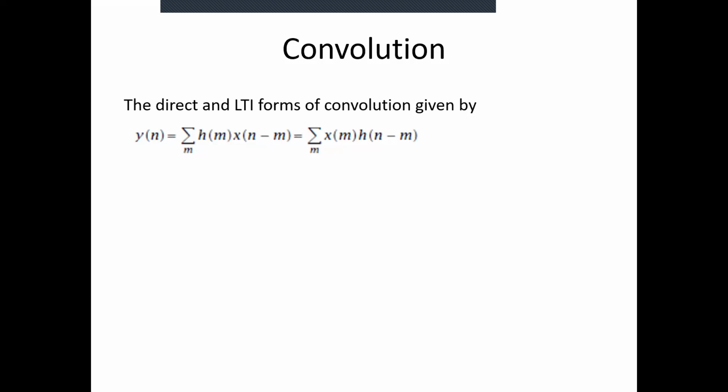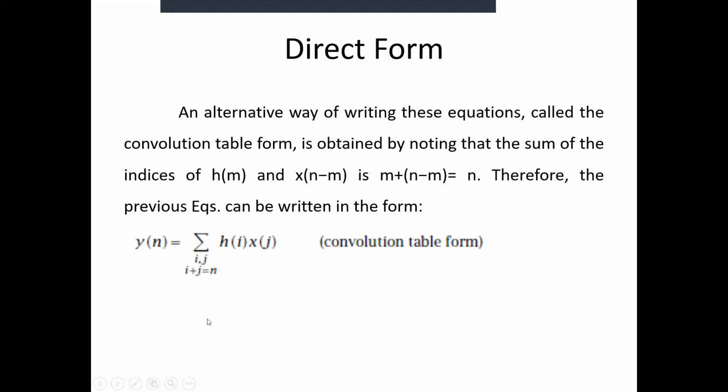Now we are going to talk about these techniques. What we are going to do in the convolution is fix one function, and the other function will be flipped and shifted. Okay. For example, in the first summation, we are going to fix h and flip x and translate it. Here, in the second one, we are going to fix x and flip h and shift. You are free either to fix h or fix x. Well, now here we have the modification.